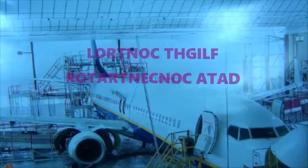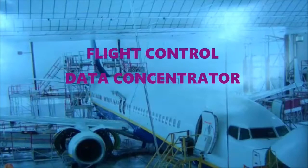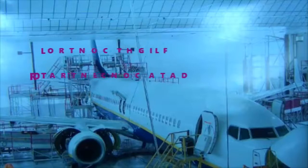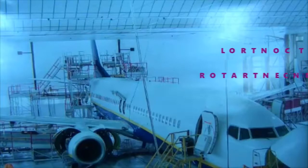That data concentration is from the computers. The flight control data concentrator is also going to generate alerts to the flight warning system in case there's something wrong. It will give specific information about what's going wrong, and those would be the messages that show up on the central management system. And then, of course, the display of that information on the flight display, right? Your primary flight display. So it has all that going on.